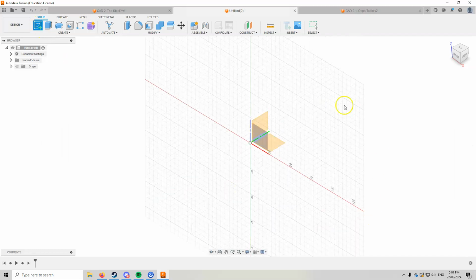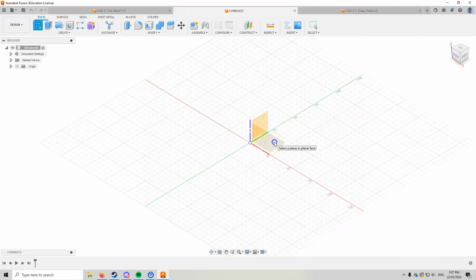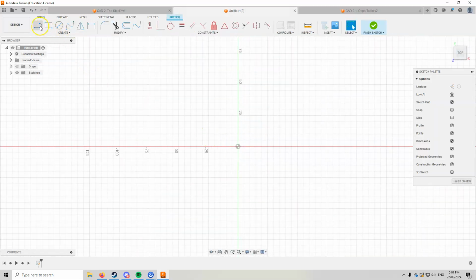Open up a new tab, and the first thing we're going to do is create a sketch on this bottom plane. I'm going to get my line tool. I'll throw a line down to the side, click the little tick, and then I'm going to press X to convert to a construction line. You can also click that button. Click the center and go totally vertical. Okay. Click X again to clear your tool. Press Escape to clear the line tool.